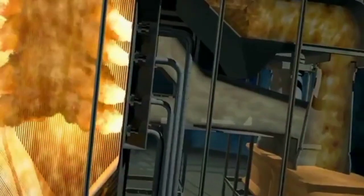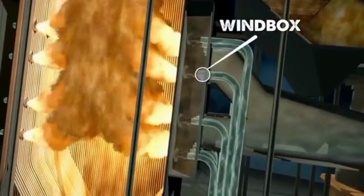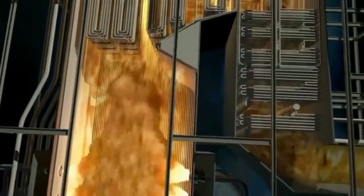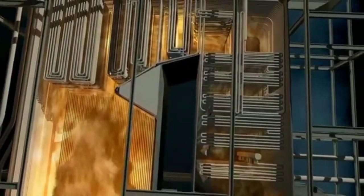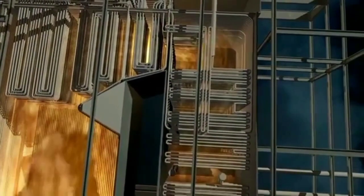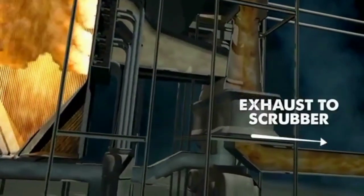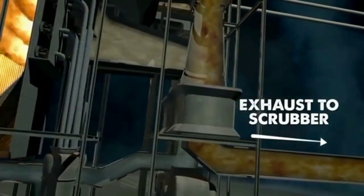The hot forced air and coal dust converge in the windbox, where the mixture is blown out through burners and ignited inside the firebox, transferring radiant heat to the water-filled tubes. The hot gases flow upward, heating the rest of the system through convection, before passing through the air preheater and ultimately flowing to the scrubber, where pollutants are removed.